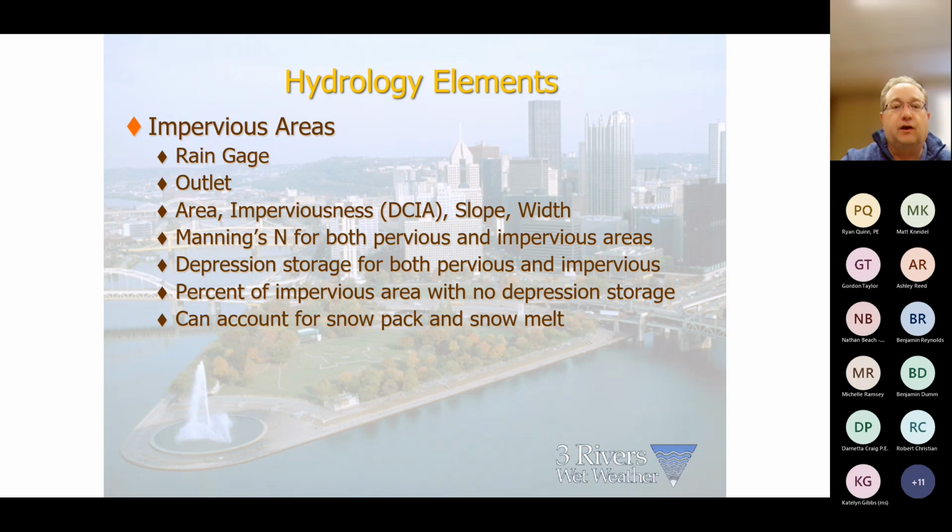That could also track with your precipitation, the snowpack and snow melt. It's also another capability of SWMM. One more comment. That depression storage, and there's another one called initial abstraction. I don't see that listed here, but those two are good calibration parameters as well.